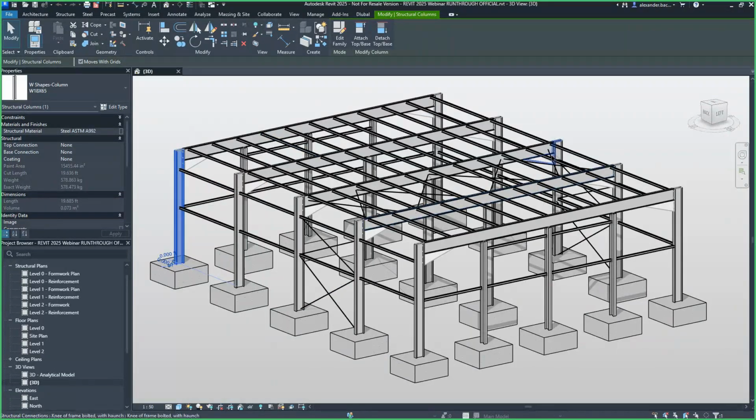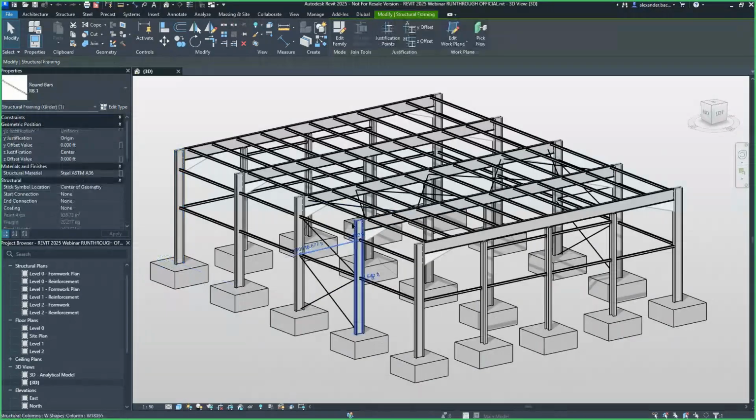Most of these are W shapes, with steel A992 for the W shapes, and then I have my X bracing assigned. And this is the structure that you would get probably from the architect. And the plan is to help the structural engineer by exporting this structure to RFEM 6.